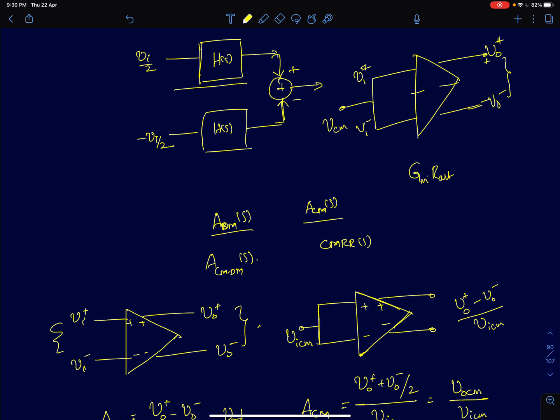If you recall from our discussions on differential amplifiers, we said for any differential amplifier, we can draw an axis of symmetry around which the differential circuit will look like a perfect mirror image of each other. And we argued that because of that, we can reduce a differential amplifier to an equivalent single-ended amplifier called a differential half circuit. By analyzing that single-ended amplifier, we can gain all the information that we need for a differential amplifier.